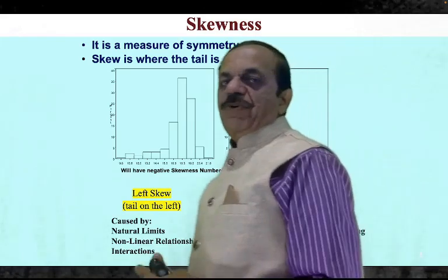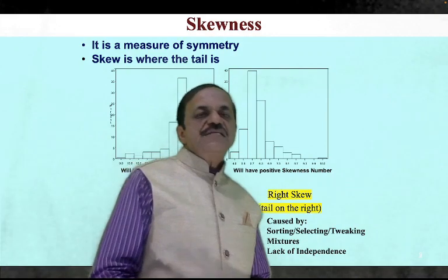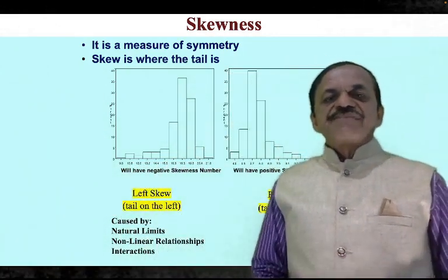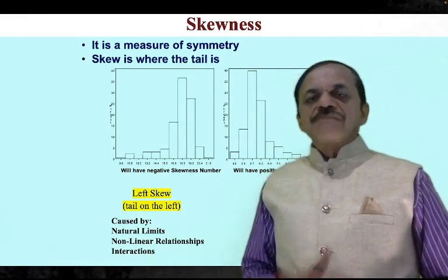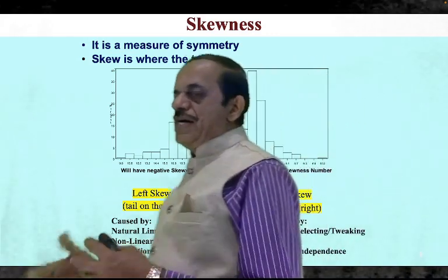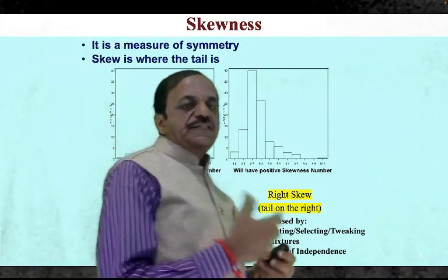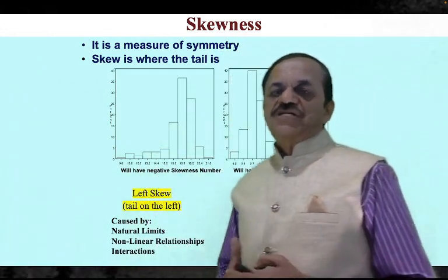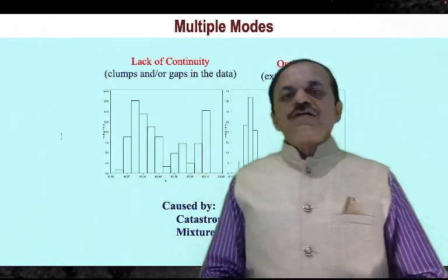Now, if the process is not good, how to identify? Instead of being symmetric, as I showed you in the previous slide, here you see this skewness, meaning there are tails. If the tail in the distribution of pillars is towards the left, it is left skewed. It means there is a bigger threat that the items will get rejected on the lower specification side, and if the tail is on the right side, the parts get rejected on the right side, that is on the higher specification side. There are more dangerous cases. See in this case, in the figure on the left, there are two peaks.